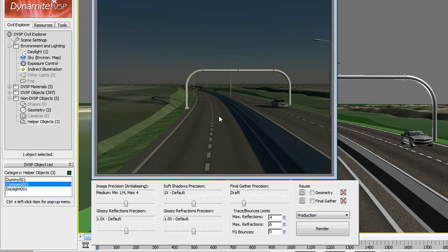And sometimes we want to do just a really quick render to test. Sometimes we need really high quality rendering in order to do a print. And the quality versus time rendering is going to be adjusted using the global quality knob at the bottom of the rendering window here. So first thing, image anti-aliasing, it's going to affect the edge of your object. So we're going to leave it to medium quality for now. For this particular image, it's fine.